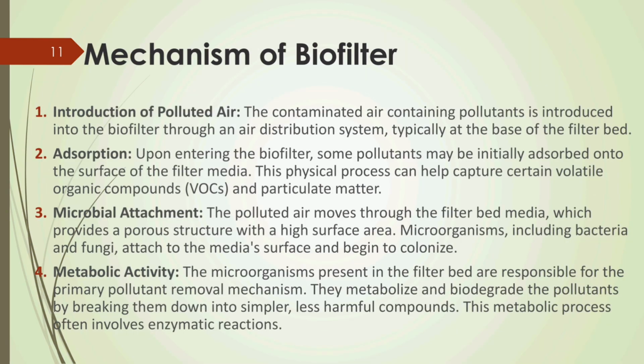Mechanism of biofilter. First is introduction of polluted air. The contaminated air containing pollutant is introduced into the biofilter through an air distribution system, typically at the base of the filter bed. Second is adsorption. Upon entering the biofilter, some pollutant may be initially adsorbed onto the surface of filter media. This physical process can help capture certain volatile organic compounds and particulate matter.